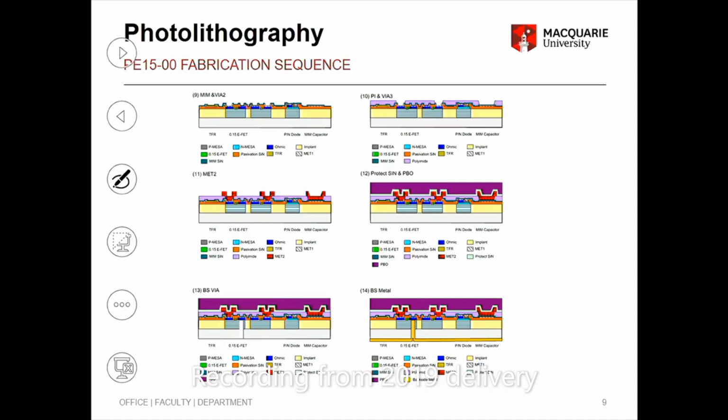You can't violate those rules. Those are the limits of the fab facility. If you make something smaller than that, they will not go ahead and make your design, or they might not care and go ahead, and you don't know whether they made it right. At least they'll give you a guarantee that if you make it within their limitations, your circuit might work. So photolithography is that.